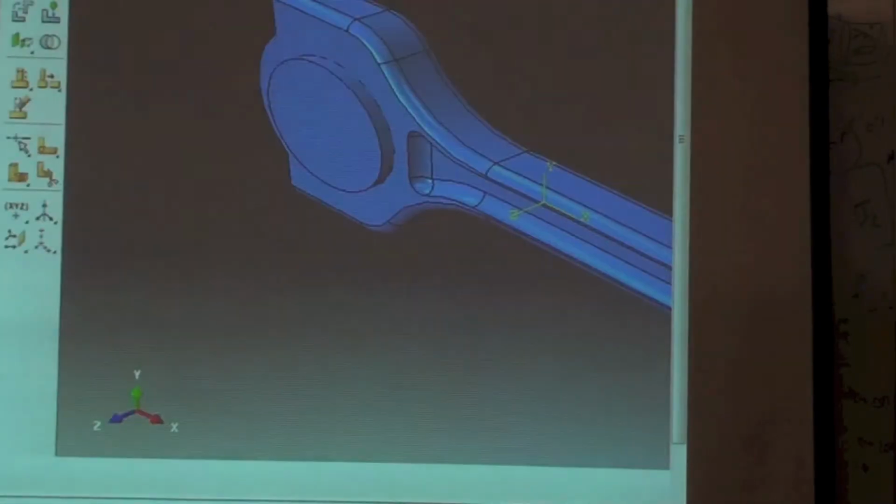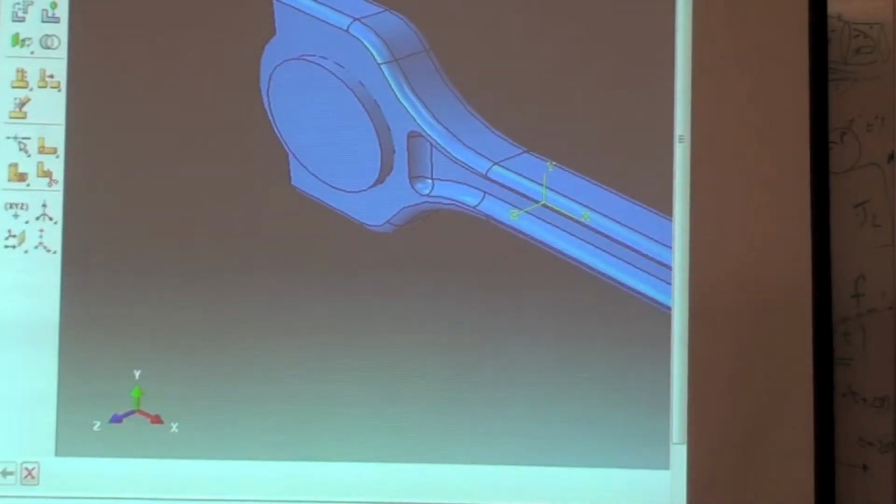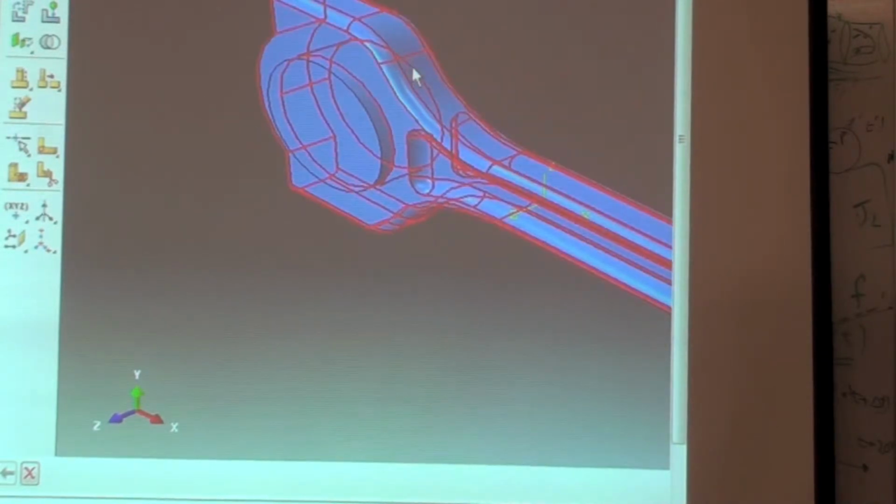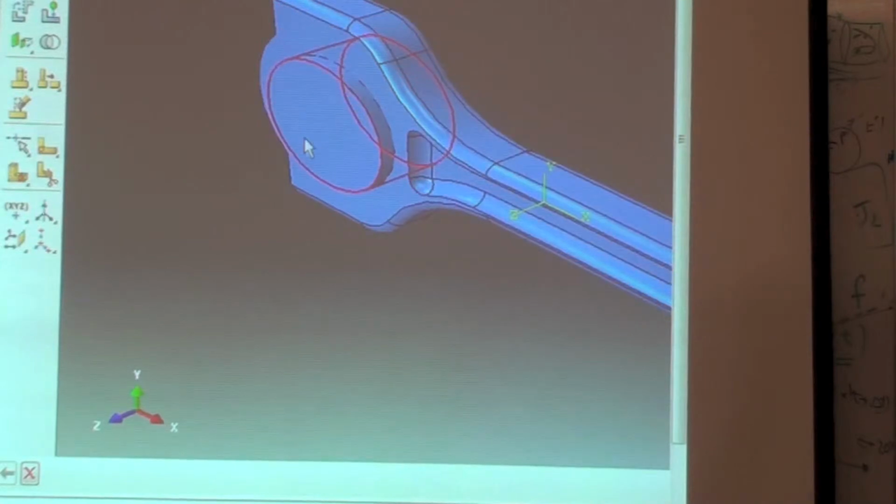Okay. So yeah, again, the assembly. This is the inner. Everything is an instance. So that whole thing is an instance. That is an instance. So you right click and you add an instance to the assembly, and then you just made them. So you can see what I did with them in the constraints. See, I put a coaxial constraint. So you can delete anything that you want. If I make a part, I can go here and I can just delete this coax. You know what I'm saying?